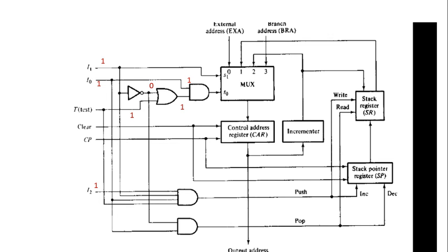Before passing control to that particular location, it wants to store the return address onto the top of the stack register file, so it triggers a push operation and the current address of our control register, incremented by 1, is pushed onto the stack top, which is the actual return address to the caller program.